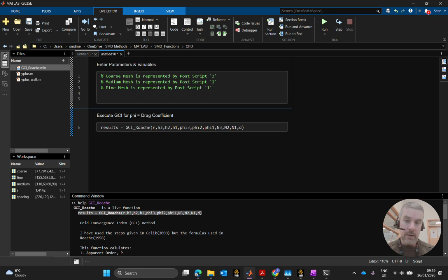If we get too fine of a mesh, we're going to start resolving things that we previously didn't resolve, and we'll find that either our turbulence model or our temporal model or our discretization model, usually the discretization model, isn't capable. It's not good enough for it. We need to change something. So that's what the grid independence is, and that's what we're going to try to get a capture on here.